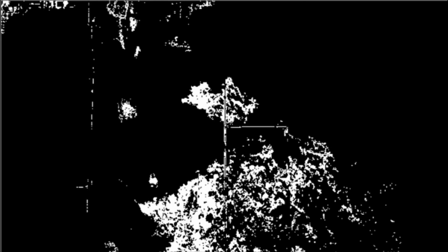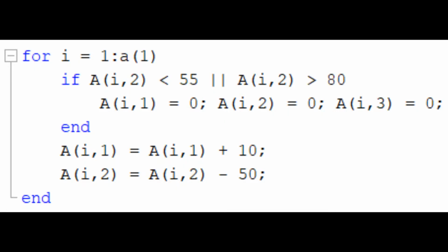Because of the varying background light, I had to create about 3 different HSV filters for each of the 4 sides, so 12 HSV masks in total. Using these values, I put the images through a script that converts the filtered images to points using geometry and the calibration parameters from earlier. Next, I took these XYZ data points and moved them over to MATLAB for further processing.